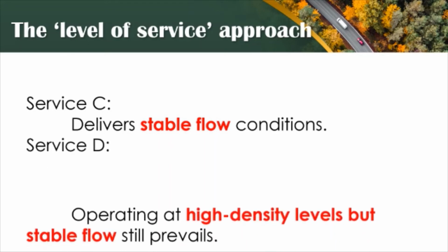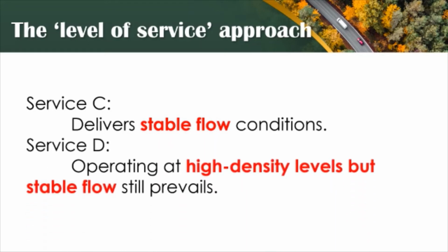Service D. The highway is operating at high density levels, but stable flow still prevails. Small increases in flow levels will result in significant operational difficulties on the highway. There are severe restrictions on the driver's ability to maneuver, with poor level of comfort and convenience.